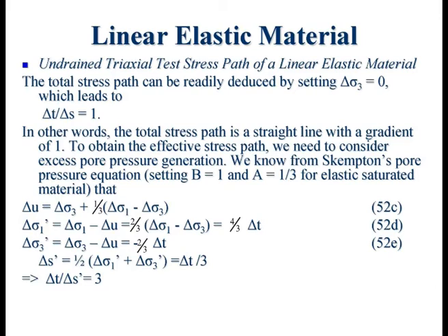Is that alright? This simple calculation just shows you how you deduce the slope, the gradient of the stress path. The first one is a very direct calculation. The other one involves a bit of pore pressure and substituting, but really nothing more than a simple set of algebraic maneuvering, and you will be able to get the total and the effective stress path.